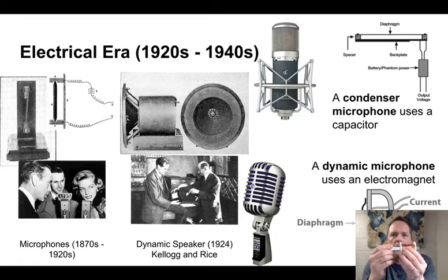When a sound wave jiggles the diaphragm, it's going to jiggle this permanent magnet that's within the coil. And what that does is it actually induces currents within the coil that move back and forth depending on which direction this magnet is moving and how fast it's moving, how much amplitude there is to its motion, all those characteristics. Again, you're taking a motion pressure wave and converting it into an electrical wave with a changing electric current within the coil. That dynamic microphone, by the way, is basically the same principle behind the dynamic speaker.